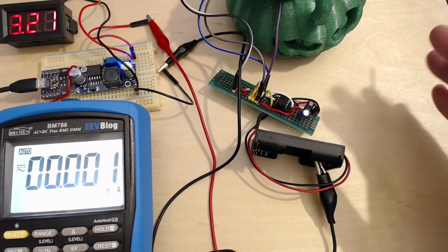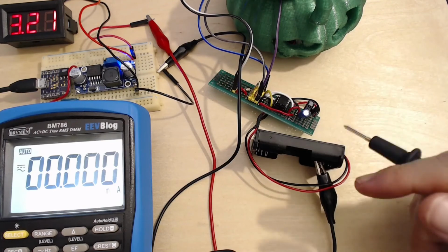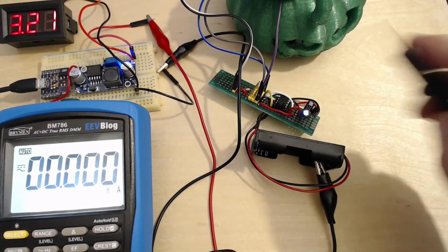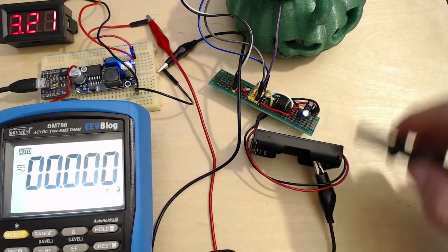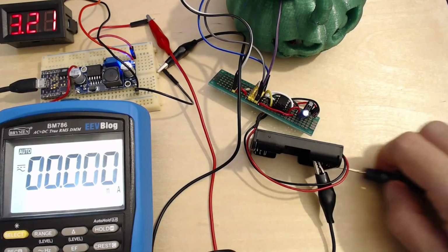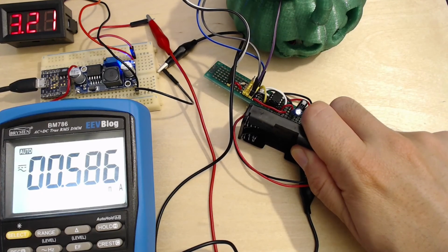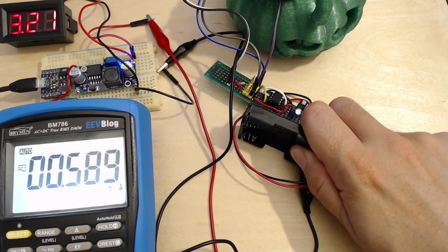One thing that I want to do before wrapping it up is just to check the current consumption at this state. I'm just going to connect my multimeter between the power supply and the battery compartment to see where we are at the current consumption. So yeah, it looks pretty good. It's around half a milliamp, and that's good enough to give batteries a little bit more time before we replace them. And that's well within the specs of our regulator and the current consumption of our micro in sleep mode.